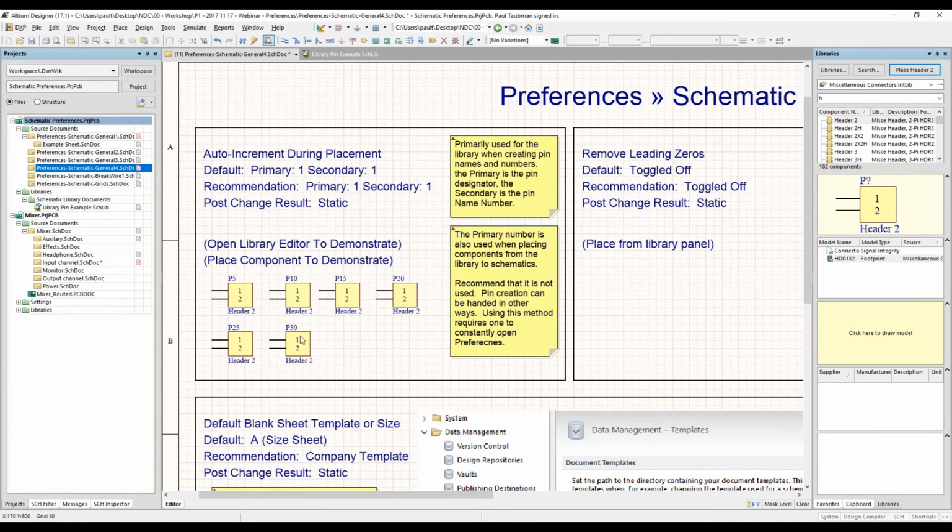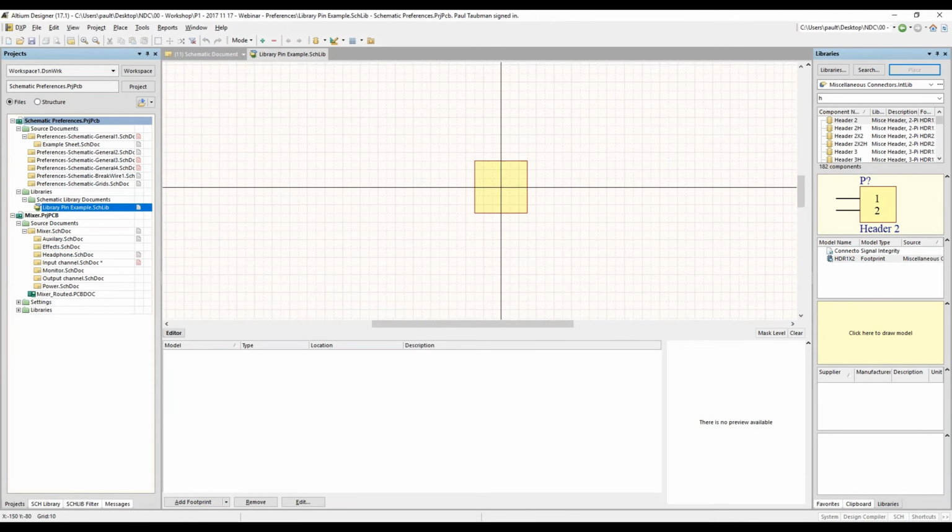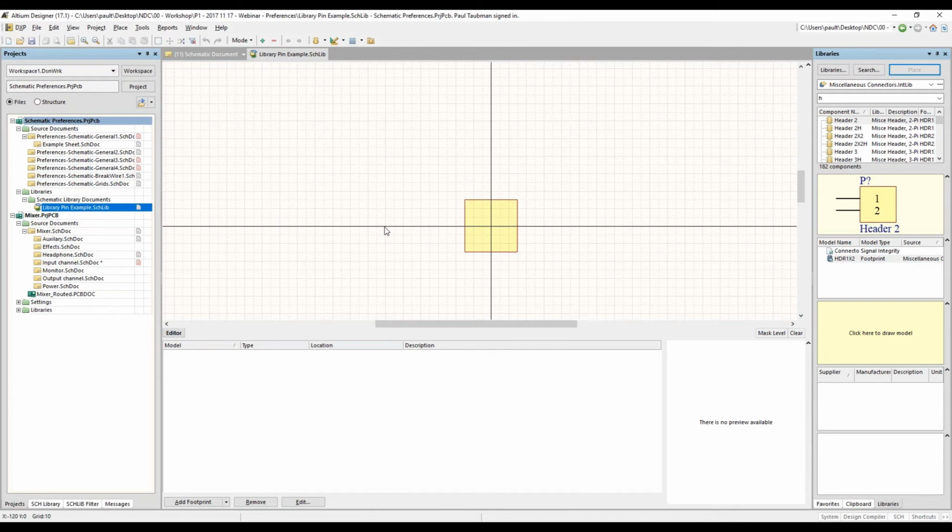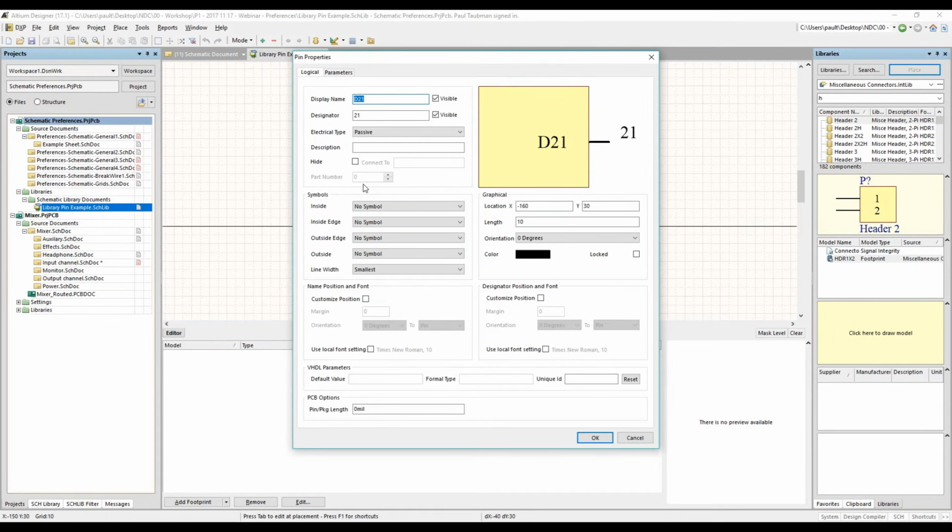It also works very, very well with pins, and I will show you a little example of this here. The reason it works well with pins is you can do some incrementing and decrementing. Now, I'm going to be honest with you. If you're still doing this over here where you're hitting PP and you're having these things increment and decrement, that's okay. I would recommend that you look at the Smart Grid Insert. That is a very, very powerful tool. It allows you to basically create your pin sets in an Excel sheet. And once you've done that, you can use the Smart Grid Insert, and it will do almost everything you need to do, including the XY coordinates if you want to do it. But nevertheless, I just do want to demonstrate this here.